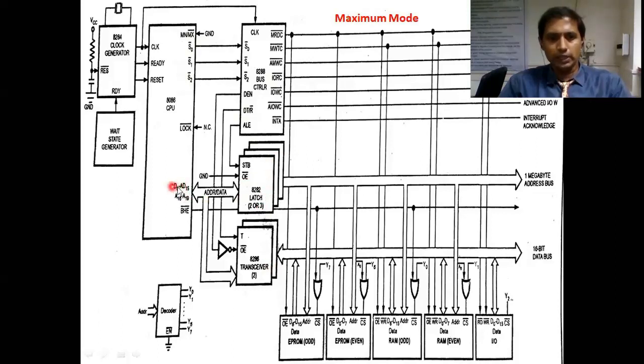Here also we are taking multiplexed address and data lines, multiplexed address and status lines, and BHE bar / S7. Passing through three latches, we get address lines, 20 address lines, nothing but 1 megabyte, and BHE bar also. This is BHE bar. After getting the address lines, the remaining lines are called data lines. Data lines are transmitted to two transceivers. We get the output as 16-bit data.